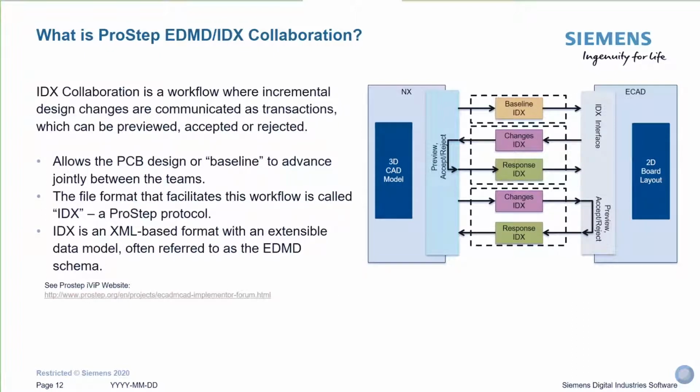The IDX or ProStep EDMD collaboration is a workflow where incremental design changes are communicated as transactions between the electrical and mechanical domains. Instead of exchanging all the time the full design information, just like an ODB++, the IDX workflow allows you to exchange a baseline, which is your initial PCB design, then advance this baseline jointly between the teams and just communicate the changes.